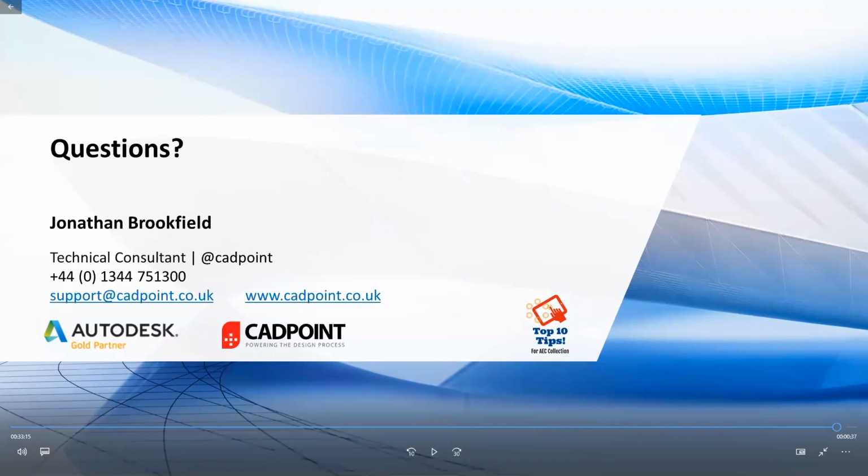I've got a question from Jeremy, backing onto detailed topo surveys into the InfraWorks model workspace. How would you integrate these survey models into InfraWorks? Mainly these would need to be processed within one of your design software, something like Civil 3D. You would create your Civil 3D surface and then bring that Civil 3D surface into the InfraWorks model. So there's an extra slight step, but it's better that way because it'll be processed properly.